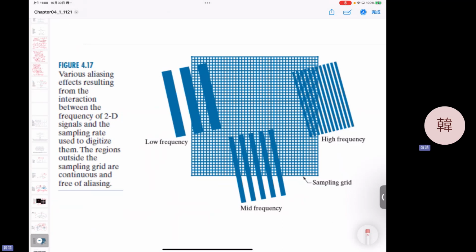Unfortunately, this one is a higher frequency, and your sampling rate is less than twice its frequency. You see the error? Immediately you can see the lines connect together, and you cannot clearly see your original. Do you see that there's a line here?